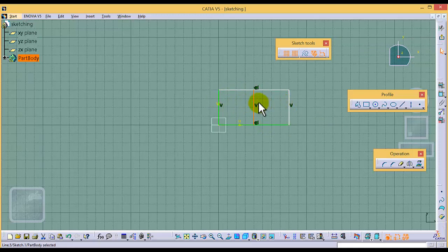So now you cannot convert this whole rectangle. You need to select both portions if you want to convert it to 3D. But if I select this one and then go to construction, it will be converted from a solid line into a dotted line, and it's telling us that this is just for a reference. Like a reference bar, you can also put the dimensions or other stuff. When we move on, you will learn about this thing.